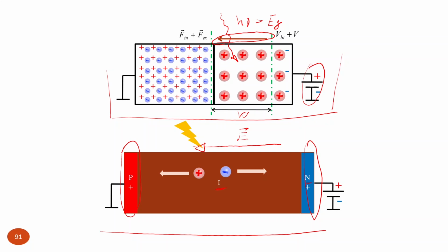For solar cell operation, if you have a really huge thickness of this intrinsic layer, which could work for a photodiode and can be beneficial because it will absorb more photons, you need to extract these charge carriers, so these holes and electrons should be extracted. Obviously, we don't have an ideal situation. Real life brings problems in terms of recombination losses and extraction efficiency, and that's why we need to apply a large external bias. With large external bias, we can improve this extraction, so we create conditions where most photogenerated charge carriers will be extracted.